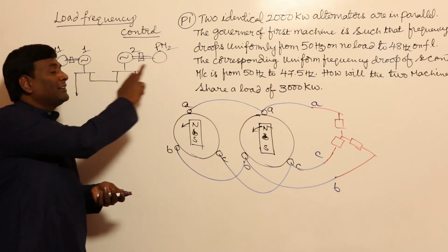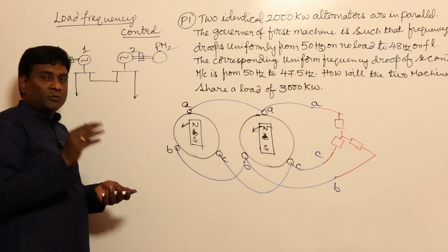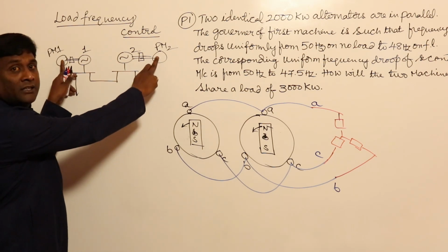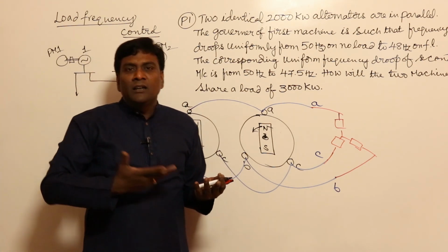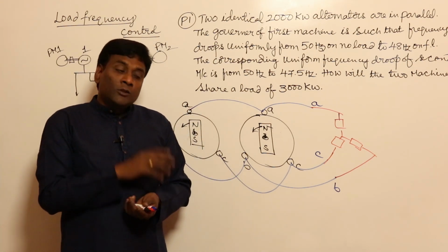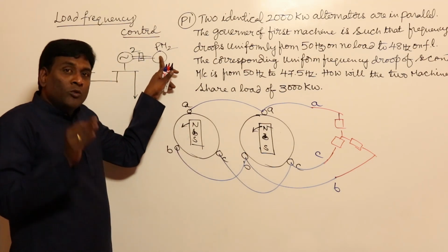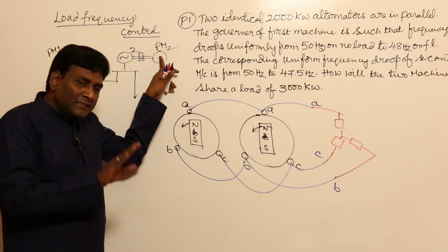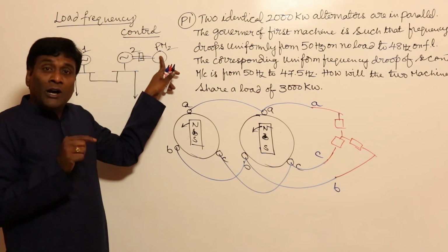And similarly in an alternator, speed regulation, I'm sorry, not speed control, speed regulation of prime movers has to be considered, because we have a huge load. All over India thousands of alternators are there, and thousands of prime movers. So speed regulation of the prime mover has to be considered. In no other generator do we consider it. In a DC generator we don't consider speed regulation of the prime mover, but you have to consider it here.